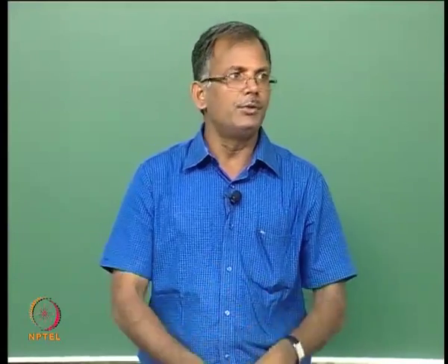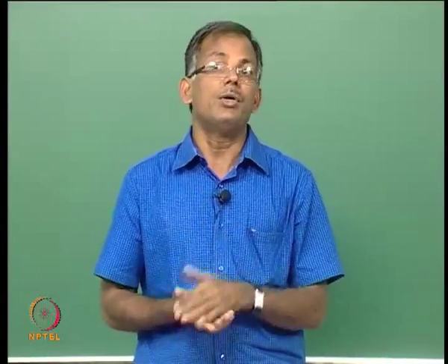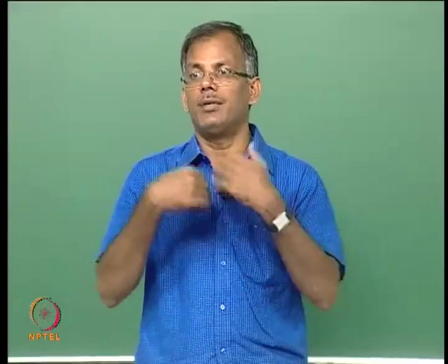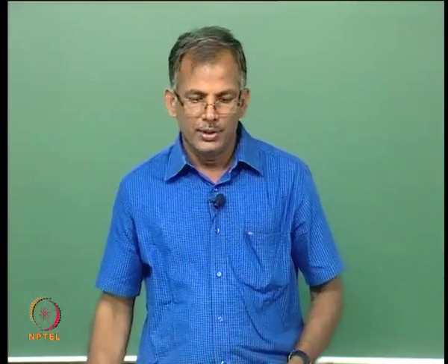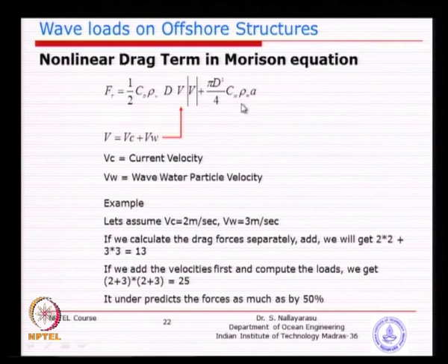So, you substitute that in this equation, because you already have the potential function, you already have selected the del phi by del x, substitute in this equation. Similarly, you can substitute the equation for the acceleration, because everything else is a constant, for example, pi D square by 4 CM rho w, and you substitute and derive an equation for F T.